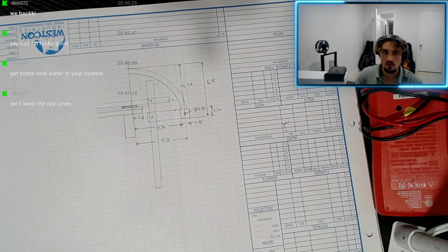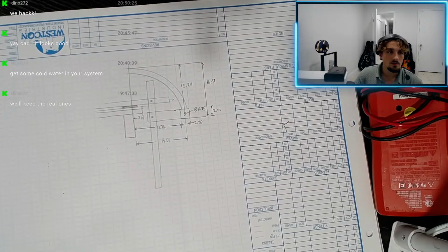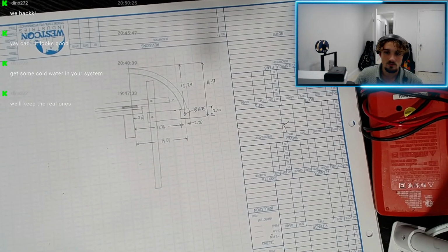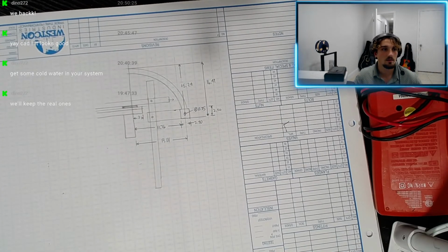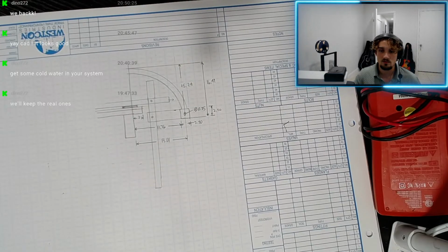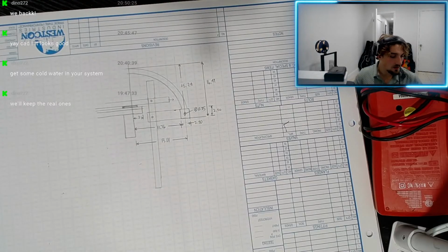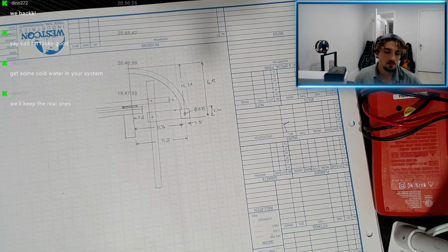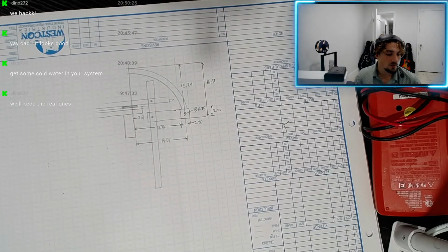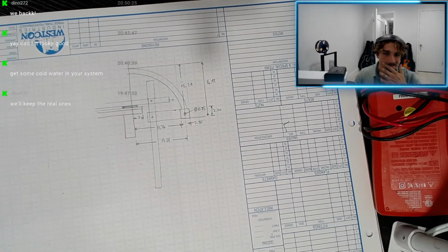How do we want to do that? That should go on top of that. And then that should go on top of that, so we'll put a hole on one side. Okay. So, features, extrude boss base, we're gonna do this side. Let's put, no, we can just do this. We can just go like that. Check smart dimensions. It's 1.5. So, 0.75. Yeah.